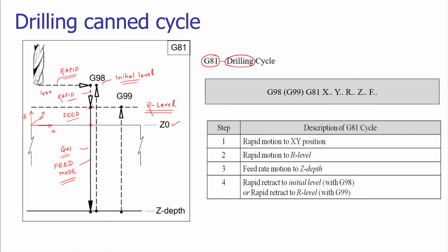The tool has gone inside, it is carrying out the drilling operation, it will complete its operation, then it has to retract. So retraction would be done using G00 in a rapid mode. So here also it is to be done with 00, that is in the rapid mode. So we are carrying out the drilling operation in the feed mode, but the retraction would be done in the rapid mode. So this is a typical cycle. These are typical operations of a particular drilling cycle.